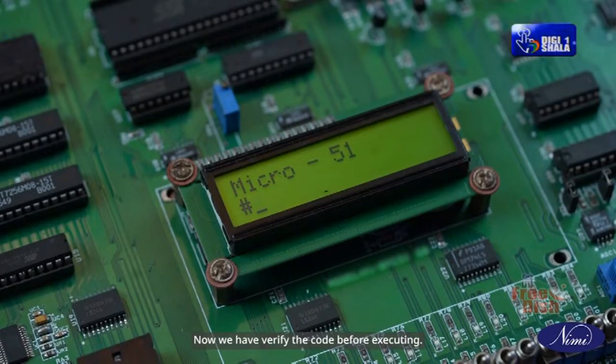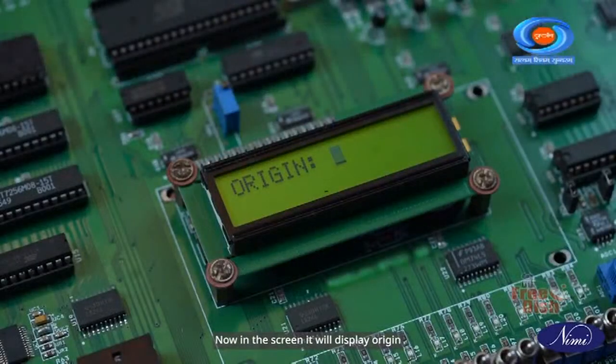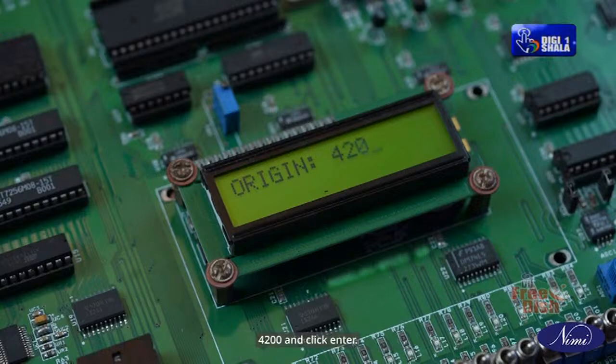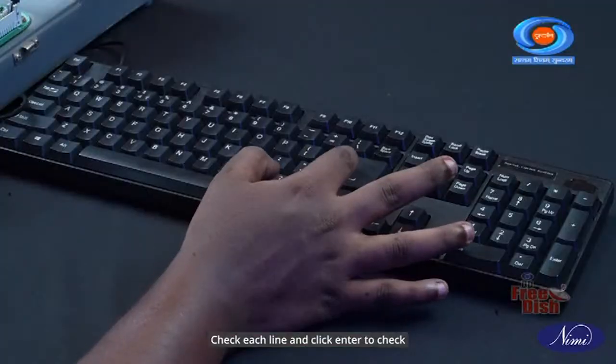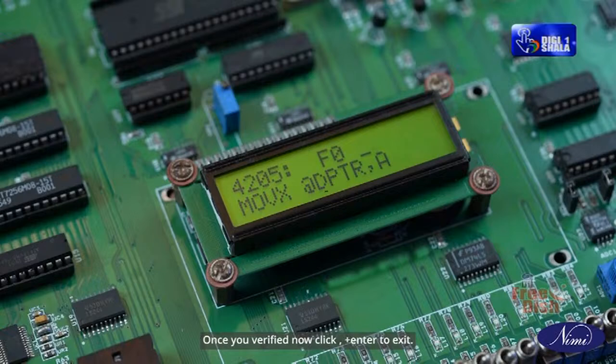Now we have to verify the code before executing. For that, click U and enter. Now in the screen it will display origin. Give the starting address of the code, that is 4200, and click enter. Check each line and click enter to check next line. Once you have verified, now click comma plus enter to exit.